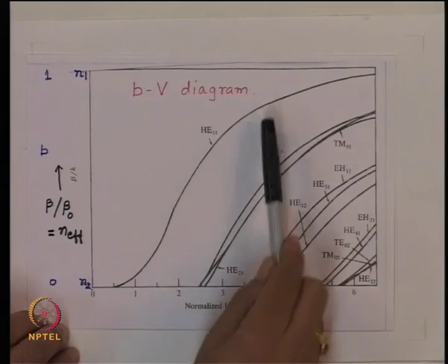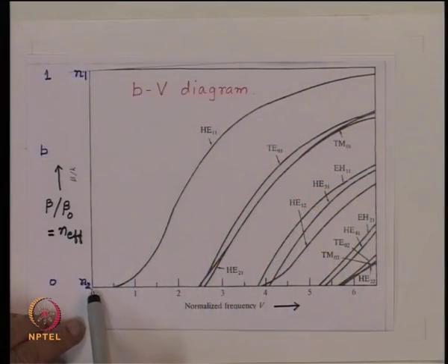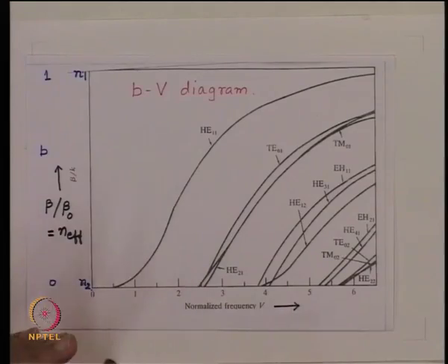And then we said this is the mode which must correspond to a ray which travels along the axis of the optical fiber. So, for single mode operation, essentially the V number must lie between 0 and this number here, which is 2.4. And then we mentioned the 2.4, this magic number, is due to the roots of the Bessel function.